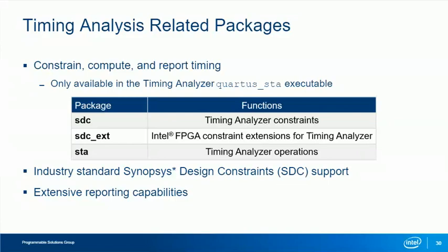Intel FPGA Timing Analyzer supports industry standard SDC timing constraints with the SDC package. The SDC_EXT package adds additional Intel FPGA extensions to the SDC standard to make constraining FPGA designs even easier. Finally, the STA package includes commands to create timing netlists, read SDC files, and run detailed reports.